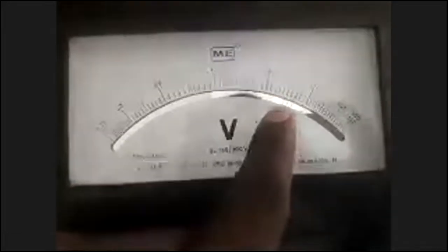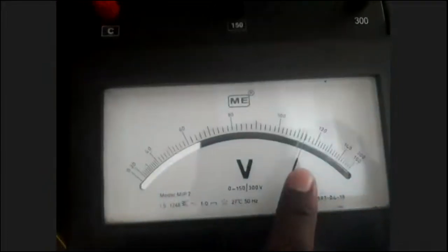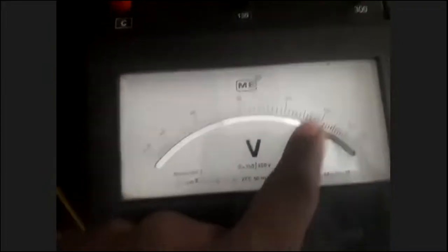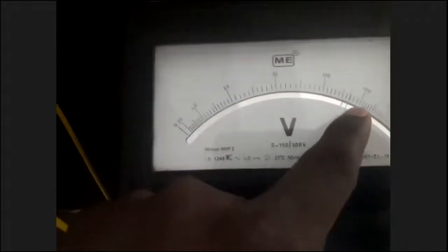Okay. See, it is 112. I have connected it to 300. So multiply by 2. That means 224. Right? Similarly, here it is also 224. That means the two side values, V2 of teaser and V2 of main, are nearly equal. Similarly, at the no load condition, there is also some flux, some current distortion, or some current should be present at no load condition.